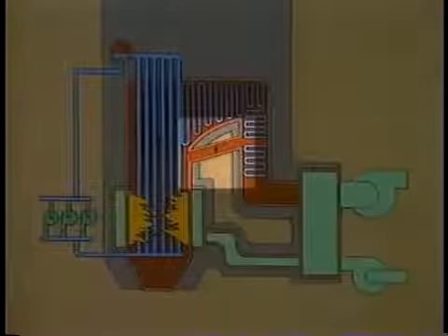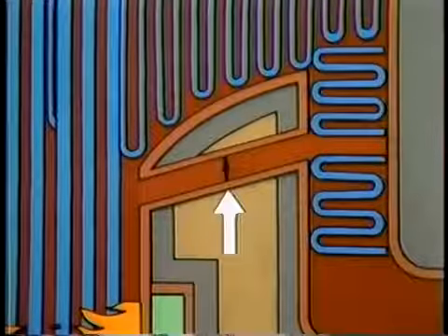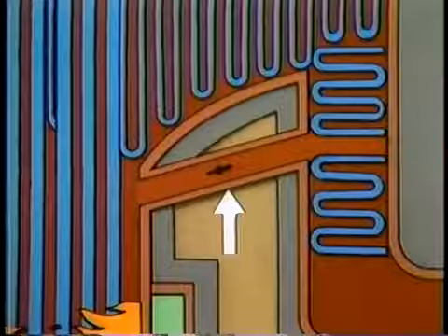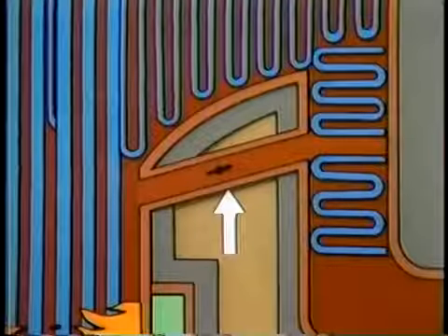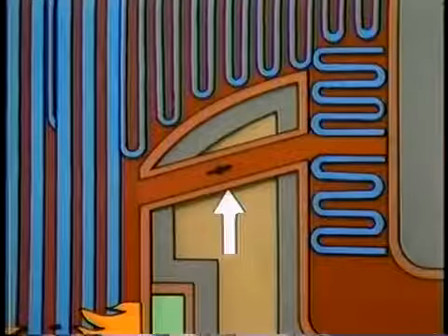In a boiler with a flue gas bypass, if the outlet temperature of the superheated steam gets too high, this damper is opened, which redirects a portion of the flue gas away from the superheaters. When superheated temperature returns to normal, the damper is closed and flue gas flow proceeds normally.